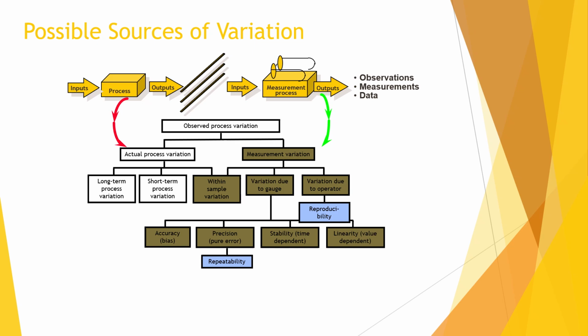Repeatability is just the variation observed when the same operator and instrument measures the same part, also called replicate or pure error. This is the fundamental error by which all conclusions regarding the interpretation of data are made. Only through a sound estimate of replicate error can other factors which may influence the data be judged. Replication is an important part of any instrument.